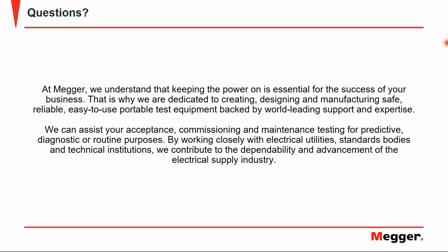The other one was in the back of the van, where I was doing testing, and that was the TDM 4540, which is a unique portable cable test set capable of performing DC testing, sheath testing, as well as VLF, tan delta, and partial discharge testing.